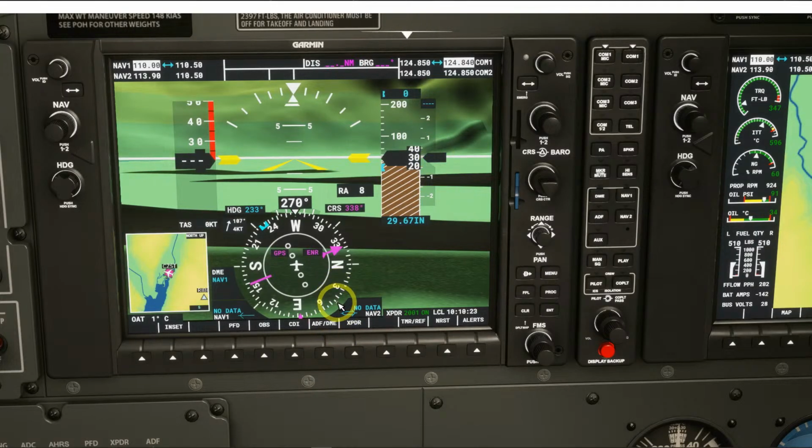If you select ILS approach, the glide slope position in relation to the runway will show on the digital square here, right on, exactly on the left hand side of the altimeter, and it will tell you if you are up and down.